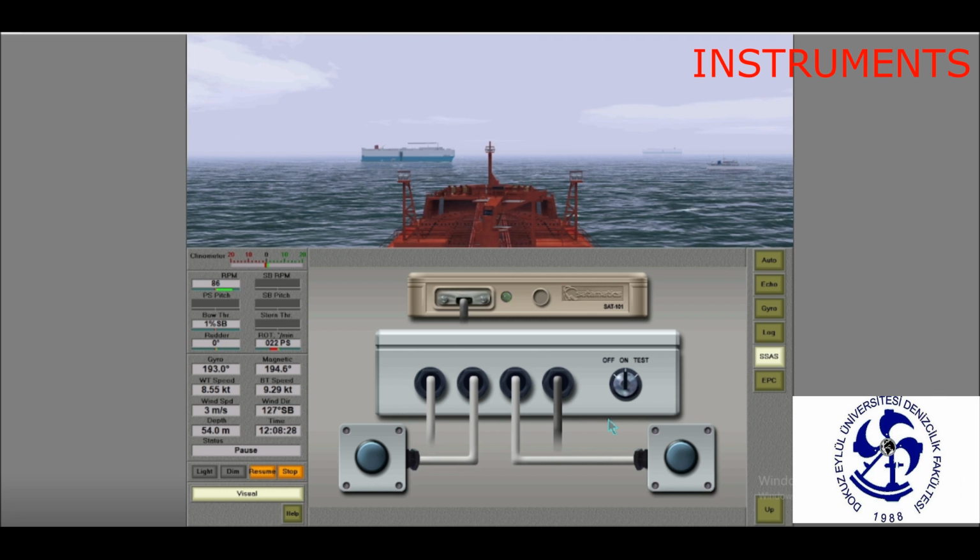Ship security alerting mode. Two security alert buttons are provided for activating this mode. The 3-position switch on the control box is required to be in the on position. To rule out inadvertent pressing of the security alert buttons, a 3-second delay in sending activation signals is provided. During this time interval, the sending of the signal can be cancelled.